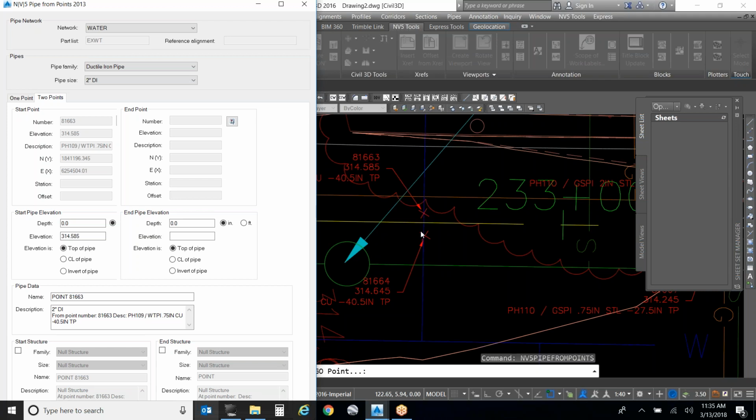It will actually be sub-X. That's the way we typically shoot it, especially in the gas group: the crossing utilities are sub-X, and that will be the designation on the survey point. So yes, if I don't enter a depth here, it's going to create this pipe at the surface elevation. So this is a must. You must enter your desired depth. If it was a sub-X point, you wouldn't have zero depth. Correct, because you're actually shooting the pipe itself. But you would still need to specify top of pipe or invert of pipe.